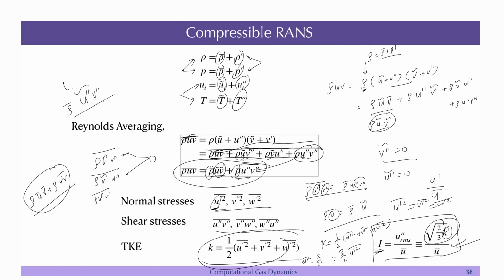Similarly, you can have the k omega model. Instead of dissipation rate, we will have specific dissipation rate. So, the unit will change, that will become 1 by second. It is related to something like frequency, how frequently the eddies are dissipating, or disappearing. So, that is the k omega model.